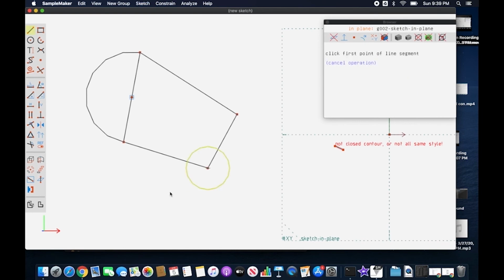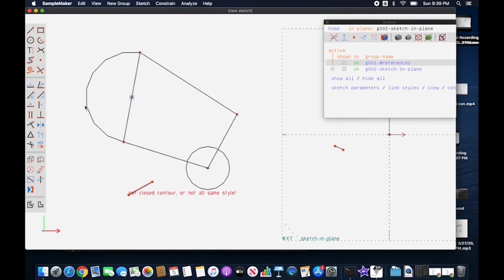And then I'm going to go and show, a lot of times too, if I'm drawing, I think you remember before we used the datum point to find points that we may not have. So here I'm going to draw a datum point somewhere, and I want that datum point to be on the circle. So I'll select the datum point, I'll select the circle and hit on, and now I can click and drag that anywhere I want.